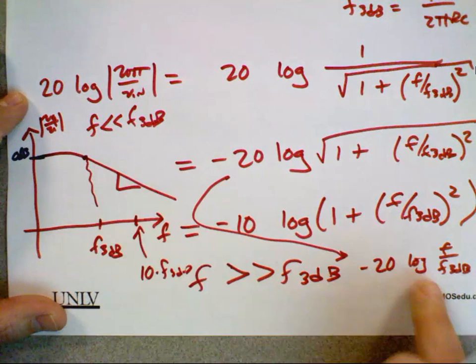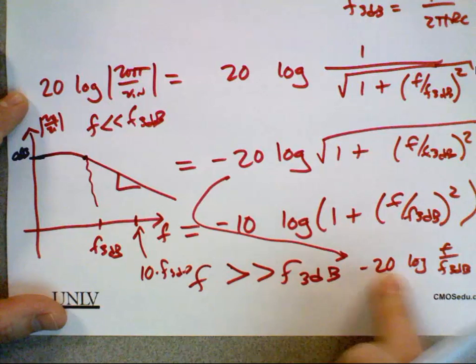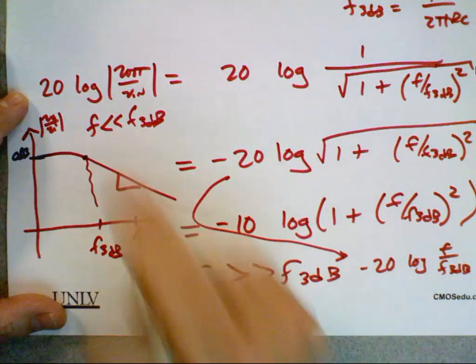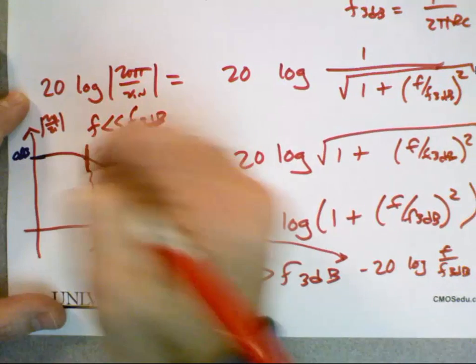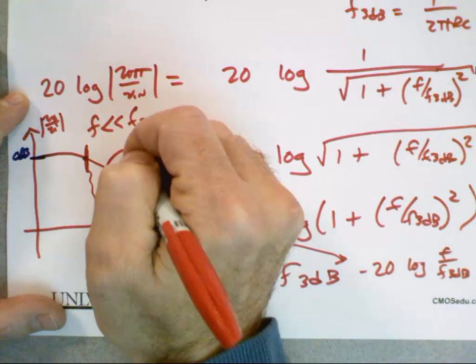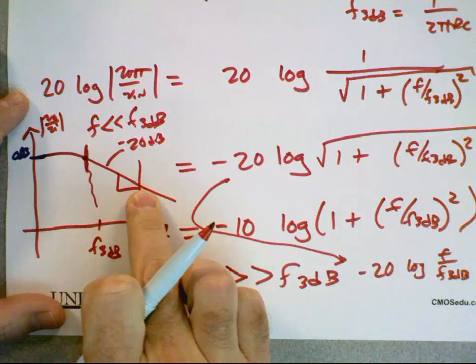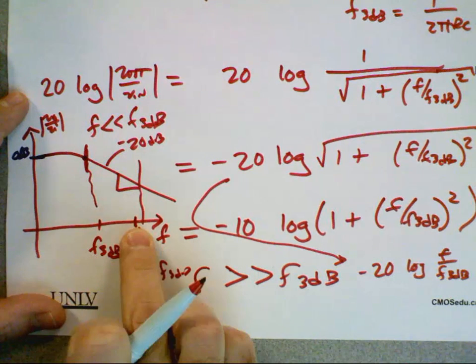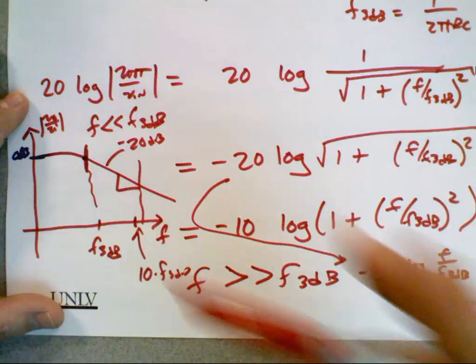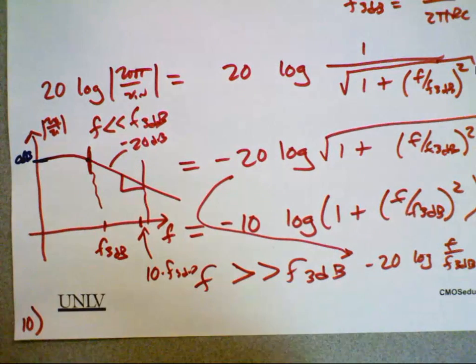Well, if it's rolling off, an increase in 10 causes a decrease of 20 dB per decade, so going from here to here is a 20 dB decrease. So for every 20 dB decrease in gain, we get a times 10 increase, or decade increase, in frequency. But we'll cover this in detail on Monday, and I'll assign some homework so you get practice, and we'll do some sims and all that. All right, let's pause and